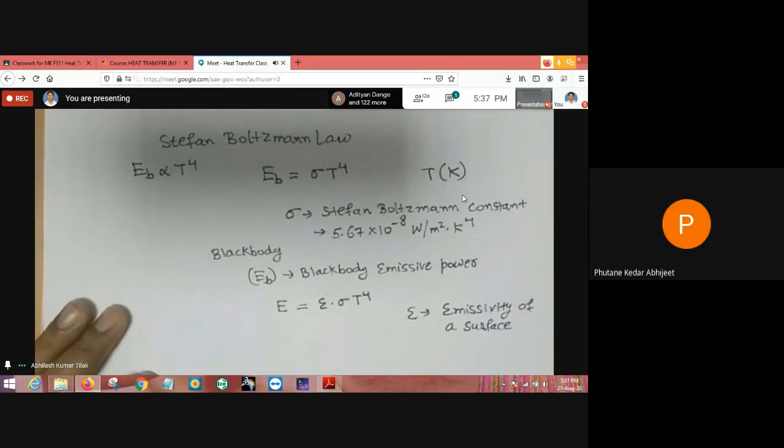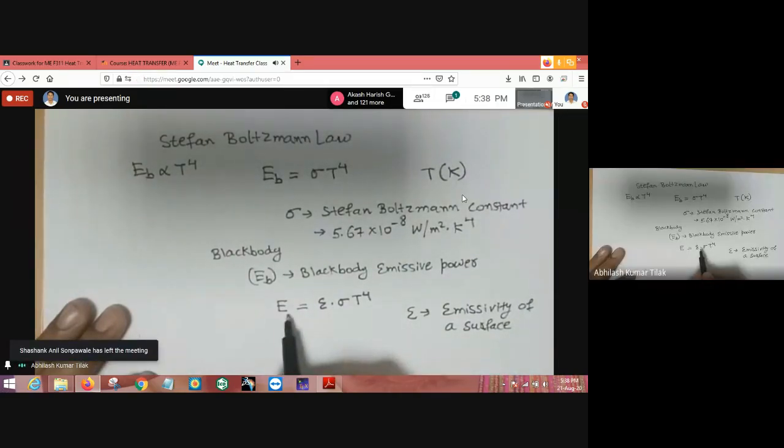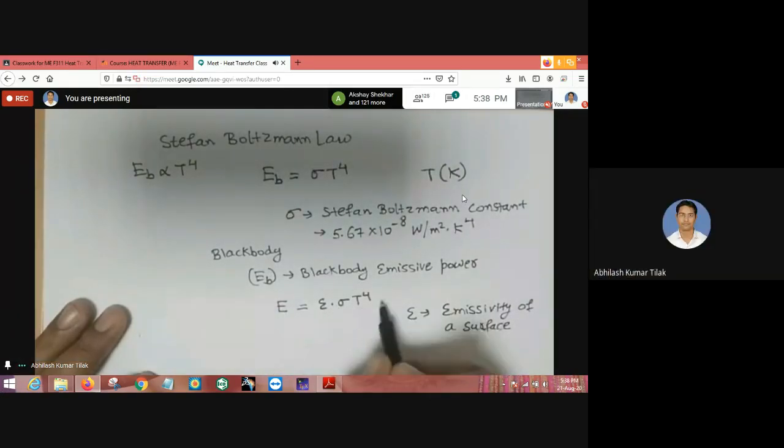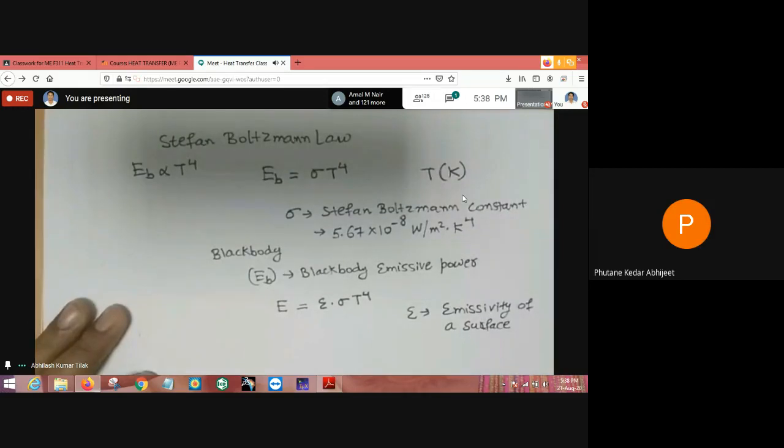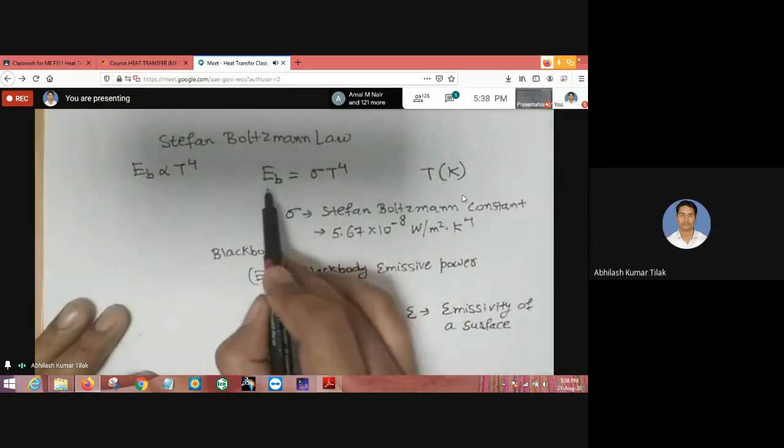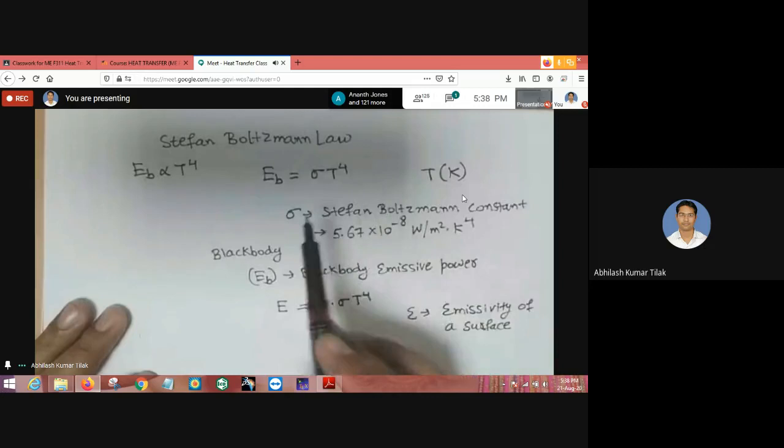Thank you, understood, sir. I referred to that as emissive flux. But when we talk about radiation, we generally call it emissive power. When we take power, we need to multiply by the area. If you are writing the amount of heat transfer by radiation, you can multiply by area here. So this is indicating your emissive flux, which is per unit area.